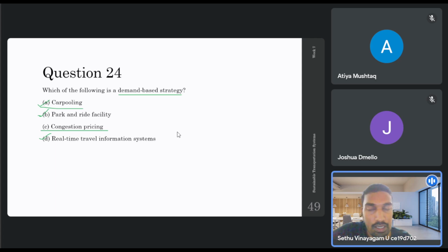How? When there is higher demand and a lot of congestion, you can go for congestion pricing. Basically, you are going to collect a toll or tax for using a particular corridor where there is going to be heavy congestion, right? If you look at how this is implemented, it will not be throughout the day. During the peak hours, when there is a lot of traffic coming in, you will implement this policy of collecting higher prices. Therefore, people will be less incentivized to use that particular stretch and will go for an alternative route.